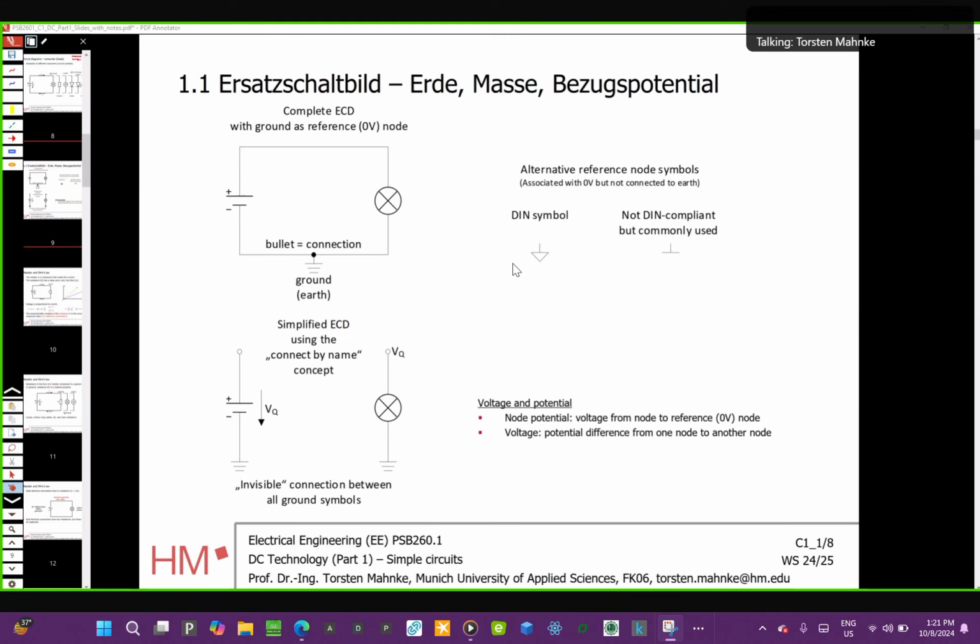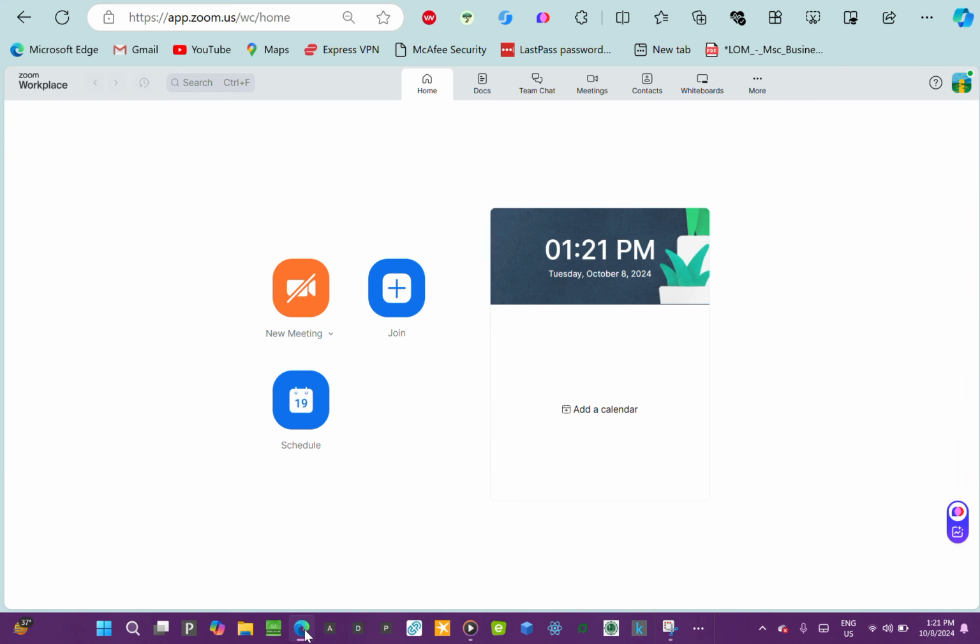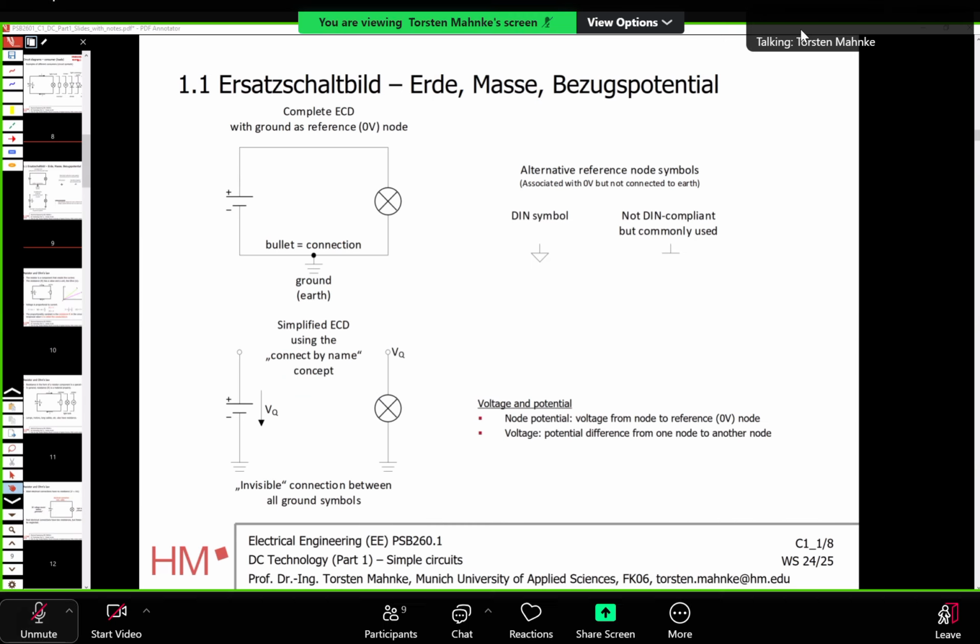Voltage is or gets connected to the metal housing, then there will be a short to earth, and the fuse will just blow off, and then you're safe. So that's the main reason. Okay, so this is the earth connection.